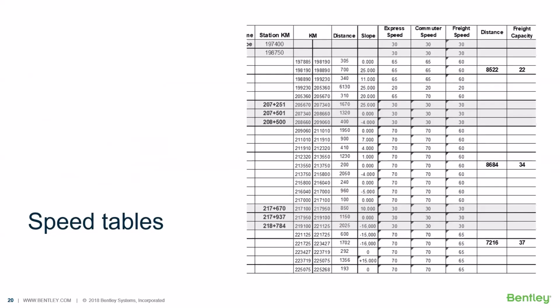If we have a look at this image right now, we can identify we have a list of different station readings, right? So we have the option to define the chainages, and then I can define that, okay, these are going to be three different speed tables I'm going to create, and I'm going to run the cant design calculation based on all three speeds. And I can identify what particular cant design is optimum for all three of these, right?